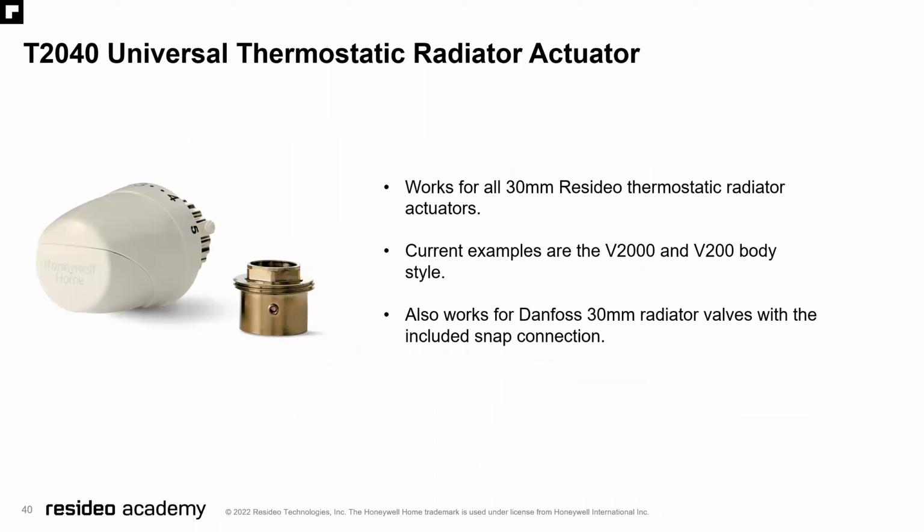The T2040 universal thermostatic radiator actuator works for all 30mm Resideo thermostatic radiator actuators. So that will fit on both the V2000 and the V200 style. Also, with the little snap connector we added, it'll work on a Danfoss 30mm radiator valve as well.